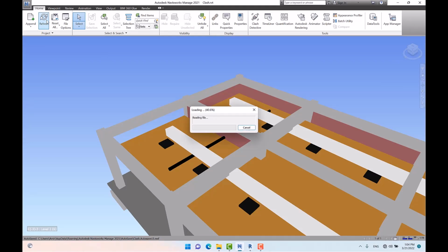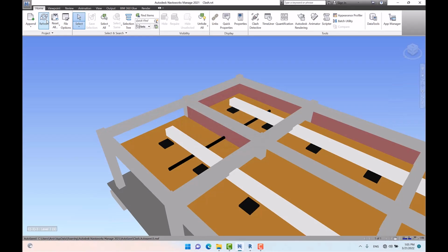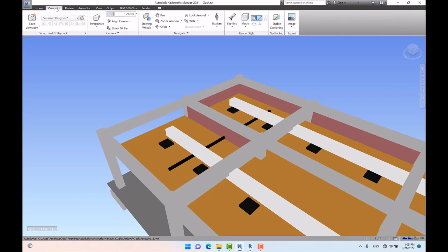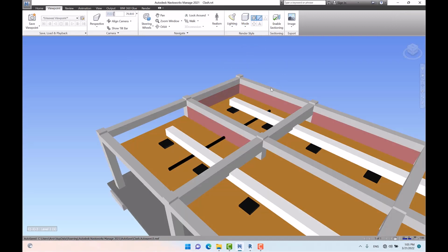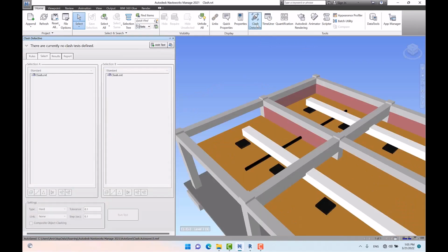And then I will continue the lesson to teach you everything about running a clash test, such as where to start, the items or objects we should specify for the standards, and so on from the beginning. Well, if you agree, I specify shaded and screen lights in order to observe the model better. So as I mentioned before, for launching your clash detection process, at first you should click on Clash Detective. Then the window of Clash Detective will be opened.